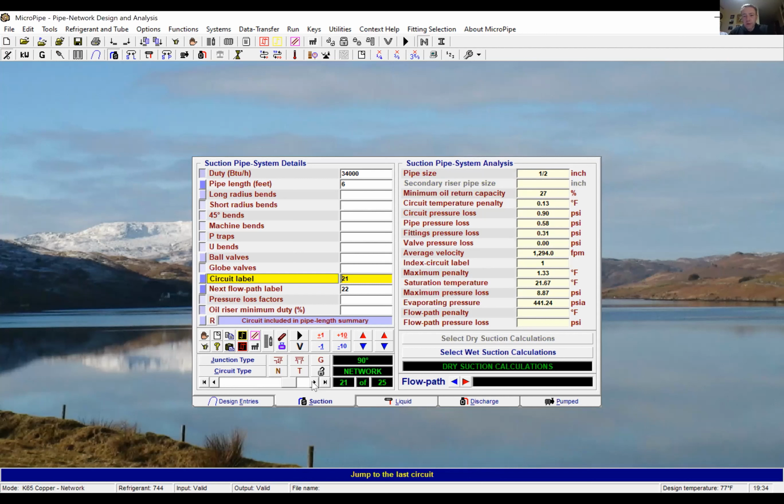So as we go through, I'm going to take you right to the end. This is effectively circuit number 25. This is the circuit which would connect into the suction header of the rack. So we've got a nice velocity of 1400 feet per minute. So we're not too high there. So we're not going to cause any disruption when we're metering the refrigerant into the compressors. And we're looking at a size of 1 1/8". Now, what I'm going to do here is I'm just going to simply...